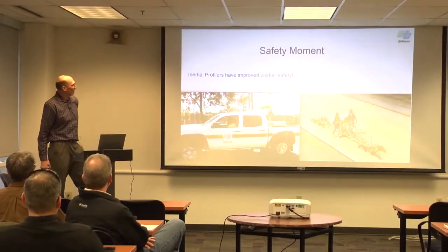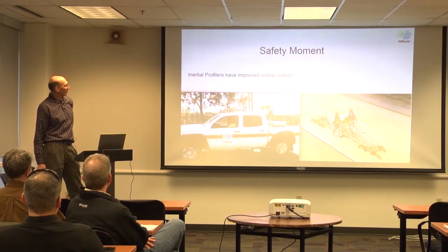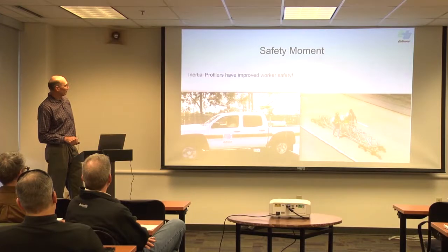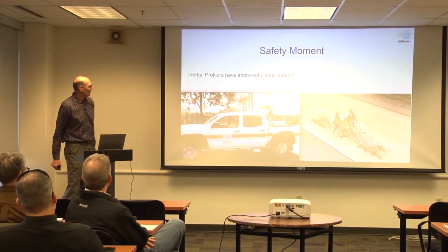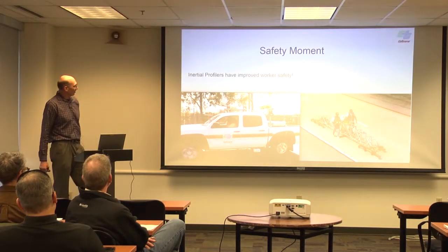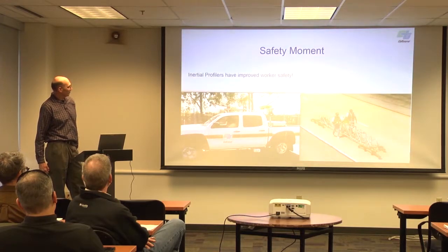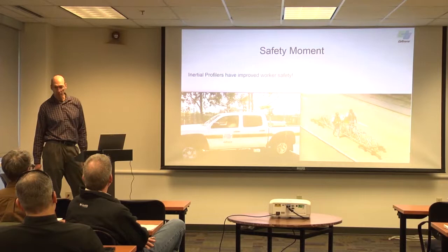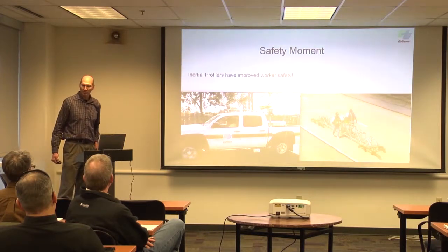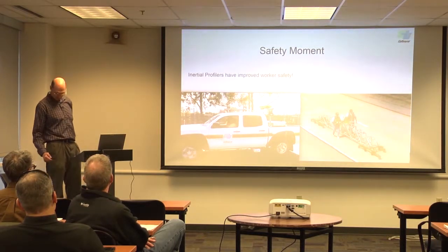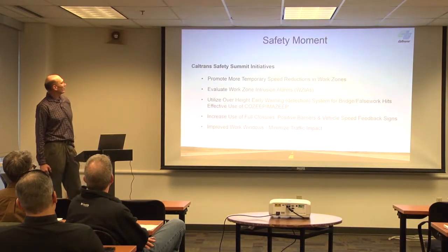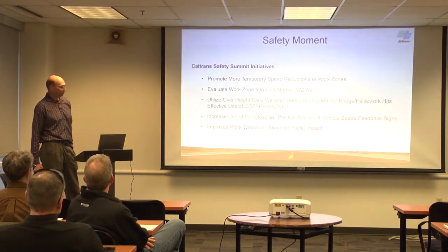I want to talk a little about how inertial profilers have improved our safety. In the past, we used to have to go out and do the California profilograph and walk the grade to check smoothness. Now with the inertial profiler, you can drive through at traffic speeds, freeway speeds, and test for pavement smoothness. And at Headquarters, there's been a lot of focus recently on safety, so I just want to share this with you a little bit.